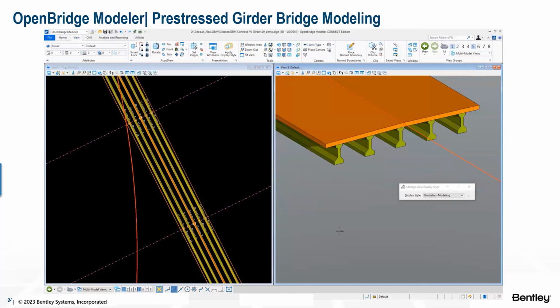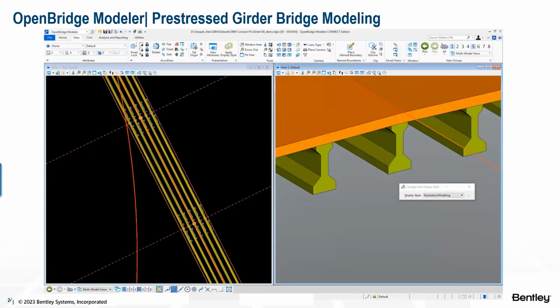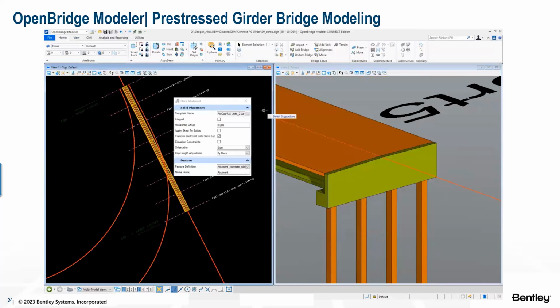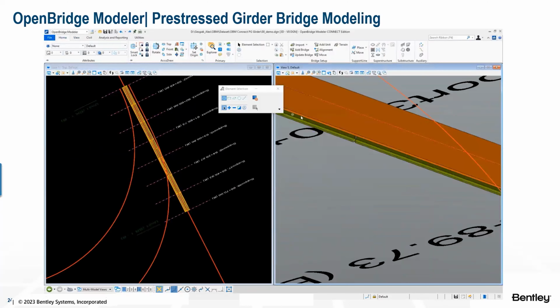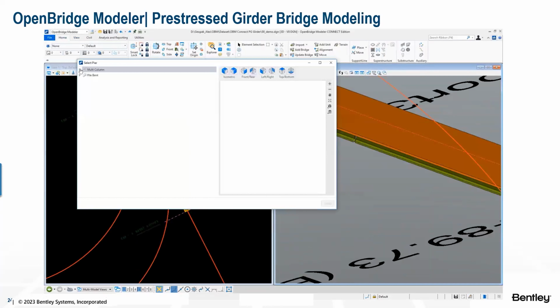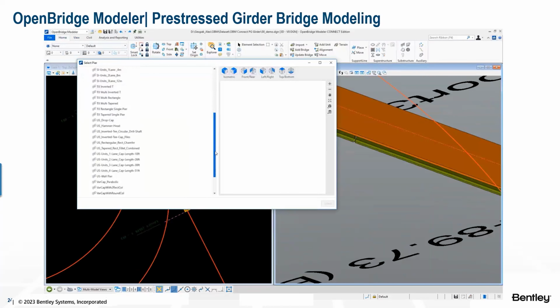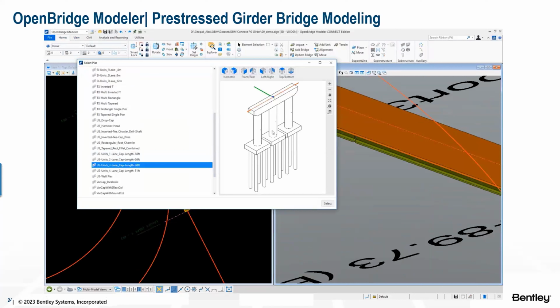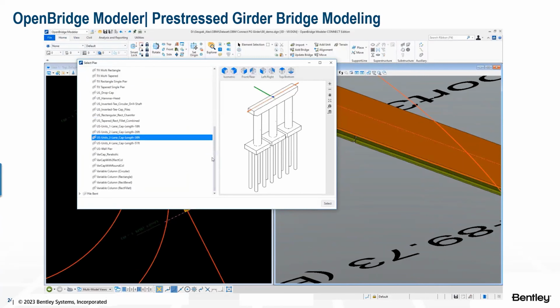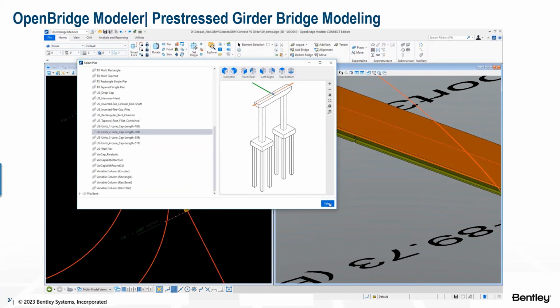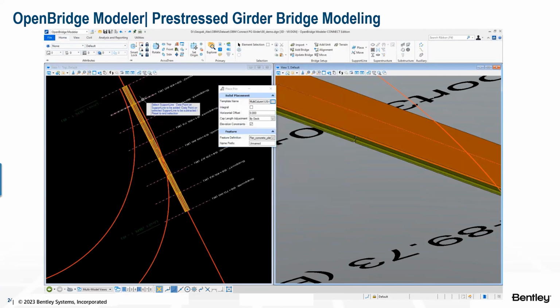So we can define that here we will have precast beams, straight beams, and after that we place the different supports. And all this is linked together. You see, we do that in this order because the piers and the supports depend on the deck elevation, but the placement of the different supports depends on where we have placed them along the alignment.